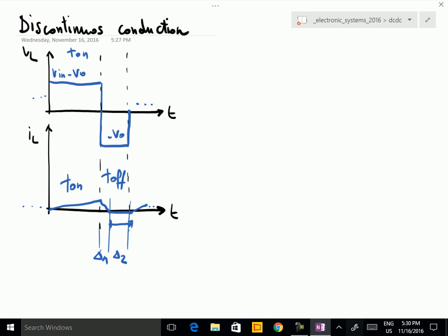This is important because the way of regulating the voltage must change at these very low currents. Regulating the output voltage just by adjusting the duty cycle, knowing that the duty cycle is the ratio of the output voltage to the input voltage, is not true anymore.